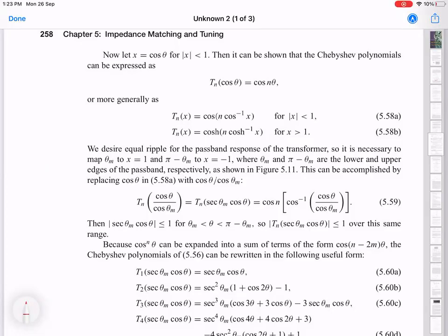If you're working with low frequencies and not fast transients, then it's okay. Everything will be very stable. But if you're working with high frequency signals, even hundreds of megahertz, you will see this affect the voltages you might get. And if your loads are also 50 ohms, you actually see the voltage will be half of what you have used. So this is something to again keep in mind: splitting signals at microwave frequencies by just taking wires in multiple directions is in general a bad idea. There's a proper way of doing that. We'll see that later in the lectures when we talk about how to split.